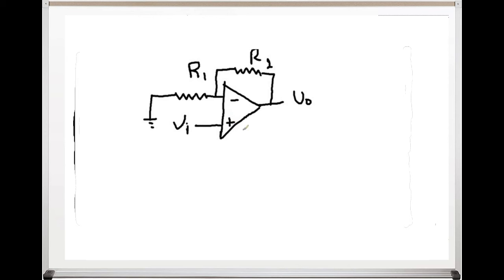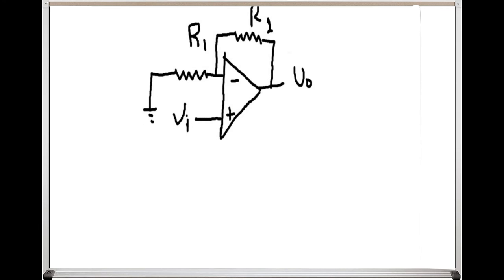The approach that we will have in order to examine this circuit and find out what the output voltage is is the same that we had in the previous one. So, first of all, the voltage in the negative input terminal will be V in, since we have already mentioned that the input terminals of the op-amp always have equal voltage.